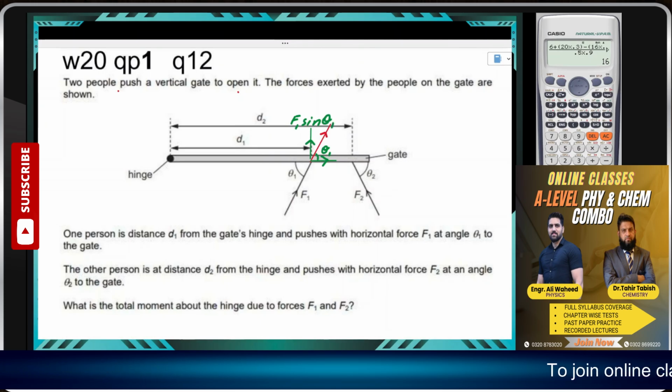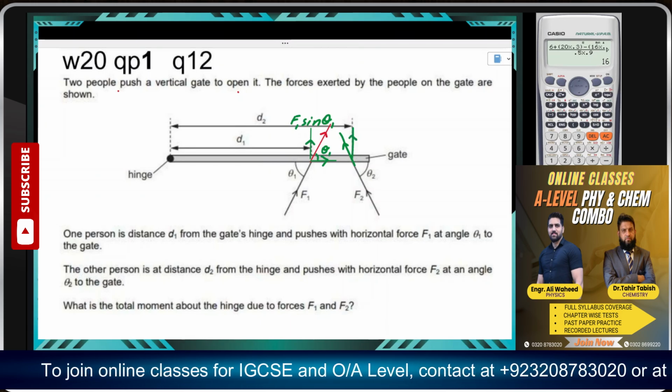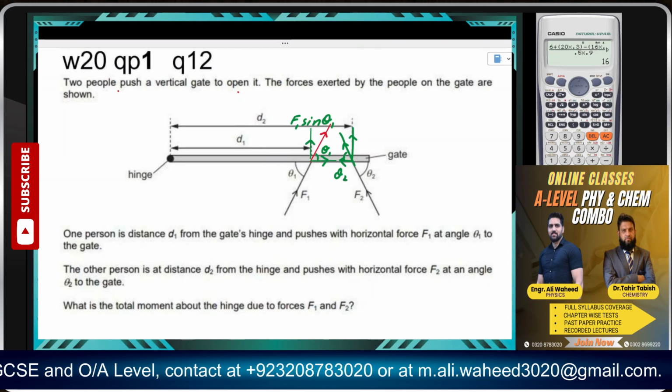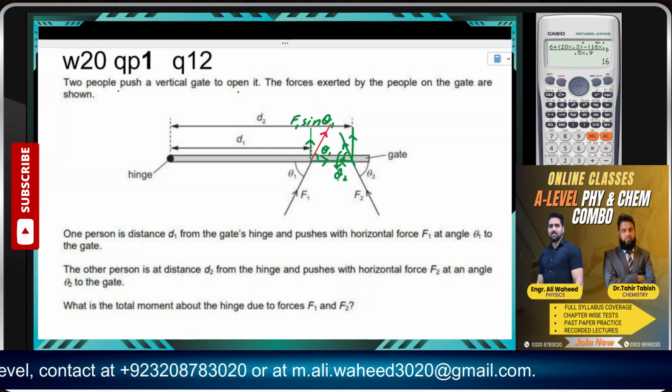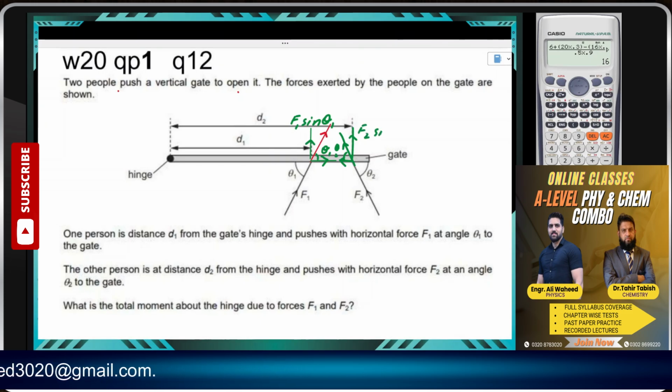The other component is touching the angle directly. Likewise, if I resolve the second force into components, I could extend the force. One component would be over here, the other component would be over here. This angle would be theta 2. Once again, this angle would be theta 2. So the component that is not touching the angle would be sine.